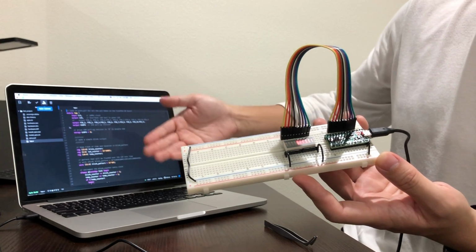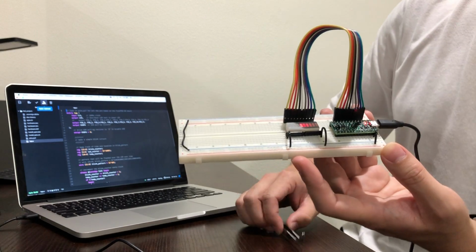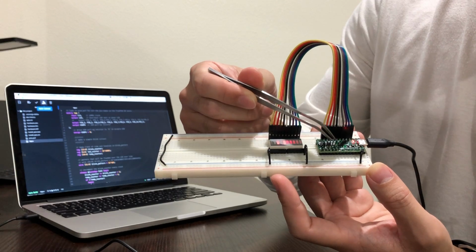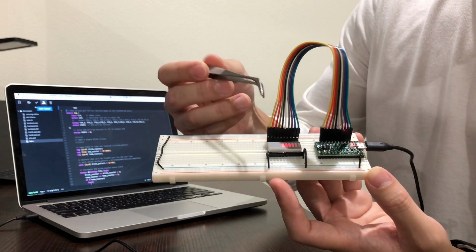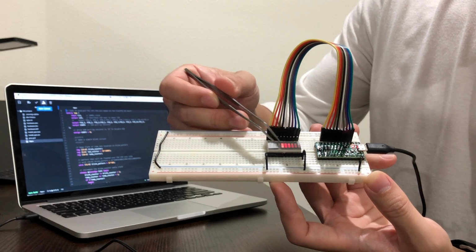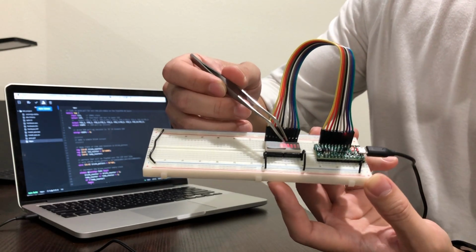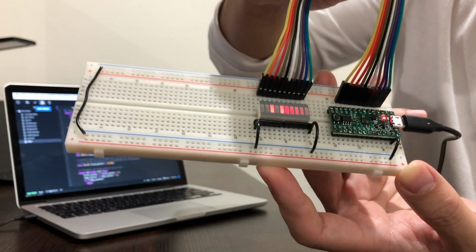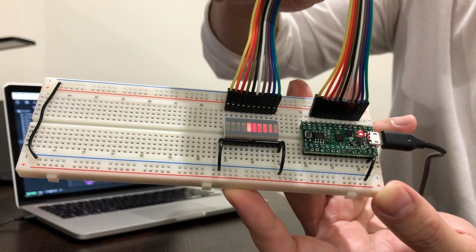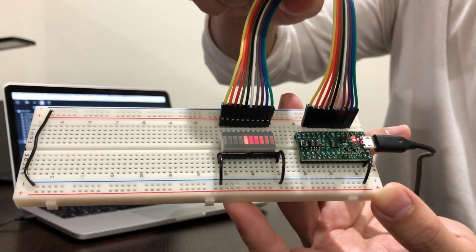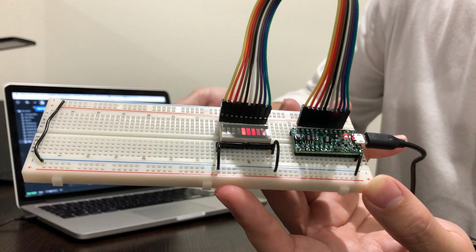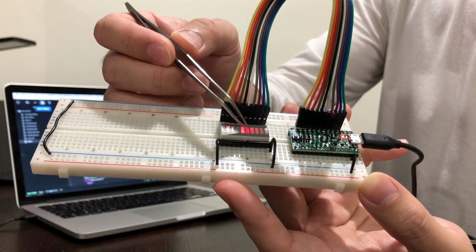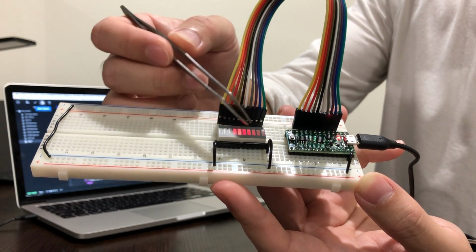And in this specific example, my Verilog code actually controlled 10 pins on the FPGA board, and through the wires, they in turn control the LED lights. So as you can see, on the right-hand side, we have 1, 2, 3, 4, 5, 6 LED lights that have different levels of brightness. So this can be easily done by controlling the duty cycle, or you can say do a pulse width modulation to the signal so that they have different brightness. We will talk more about it in the future.